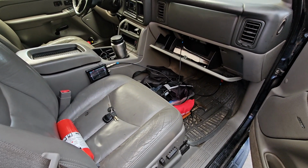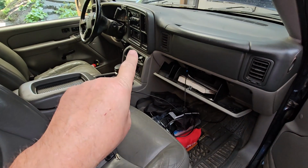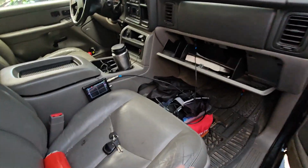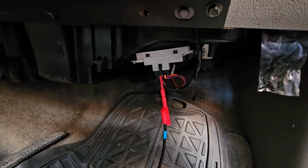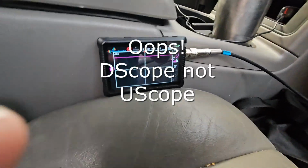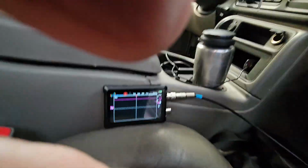But I had to get an oscilloscope out because the signal that was coming from the head unit, temperature control unit there, to the electronic motor control, I was suspect of it after doing a bunch of measurements. So here's what I've got set up for measurement. I've got a needle pin in that control wire there. I've got a ground wire hooked up into the frame here. And I've got the U-scope set up here. So I'm just going to put the keys in and we will turn the motor on.